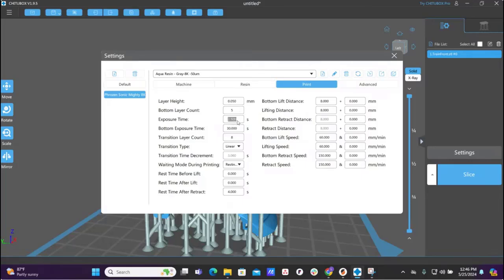So if you're doing resin prints and you have a bunch of fine details, let's say like fur on a fox or, I don't know, a wolf, right? And you're not seeing the fur, it just looks kind of muted. You probably have too much light, and so it's overexposing, and you're not getting your details. And you'll want to turn that time down. Maybe instead of 2.5, you go to 2.3 and print again, and go to 2.1 and print again, and then you pick your favorite. And then there are calibration test prints that you can find that help you dial in these settings.